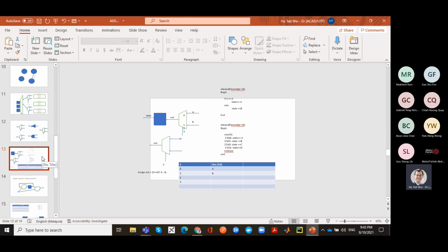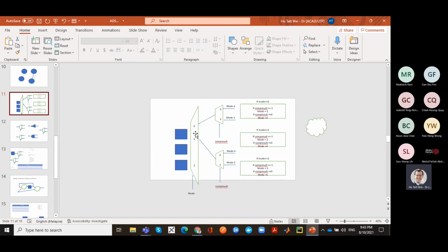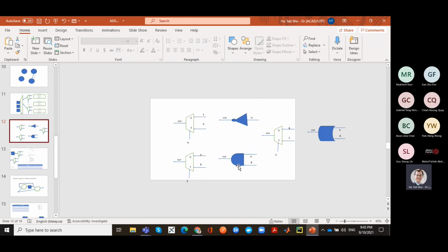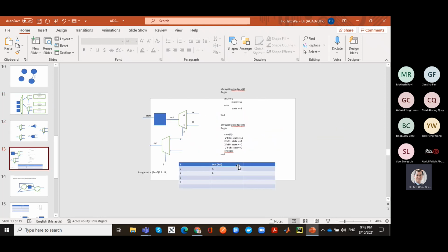And you know that you can always convert this multiplexer representation of digital logic into AND or NOR gates, no problem. The synthesis tool could do that. Otherwise, you can just implement a multiplexer as AND or NOR gates, and then you can do your Boolean optimization to reduce the number of gates. No problem. You know how to interconnect that.